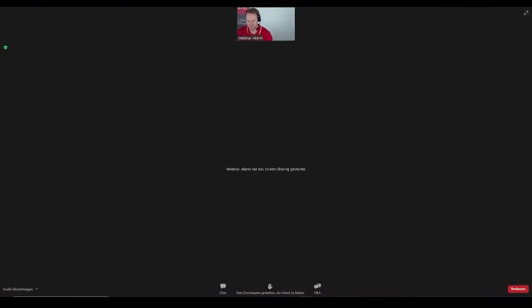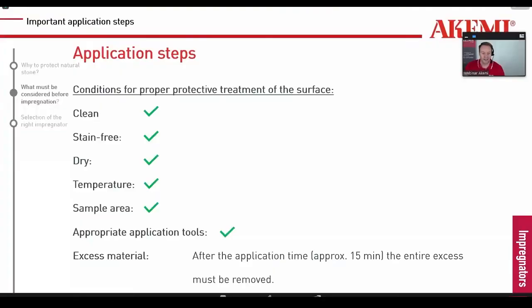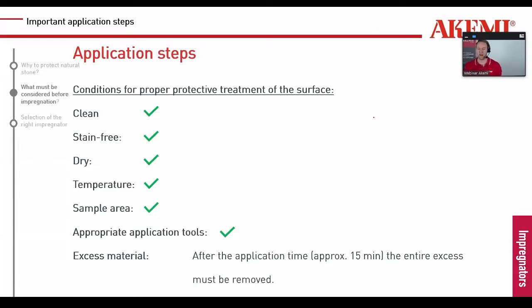Excess material. As I said before, usually 15 to 20 minutes is what we recommend. We have some sealers that need less time, and we have some sealers you can leave up to 60 minutes on the surface. But let's say an average between all sealers and impregnators is like 15 to 20 minutes. You should leave them on the surface, and after that, you have to remove the entire excess, which is not absorbed by the stone.